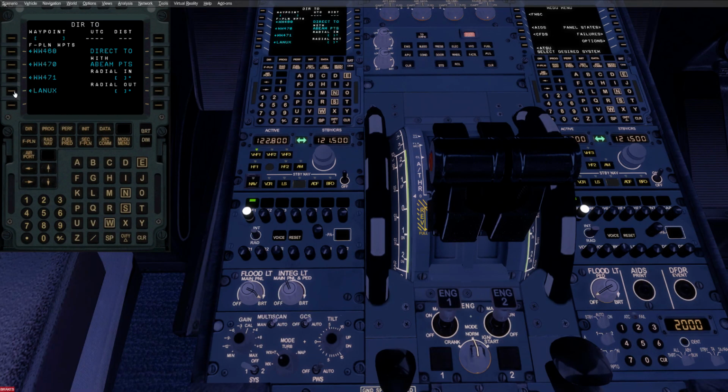Then you could just select that waypoint and then insert it, and it will set your navigation and your flight plan so it's taking you direct to that waypoint. It will delete all the waypoints that were on the way, but it keeps the rest of your flight plan after that. So it really just lets you skip some waypoints and head to a certain one that's already in your flight plan, and then you'll proceed on your flight plan from there, all on autopilot. Or you can just put in any random waypoint and head to it.